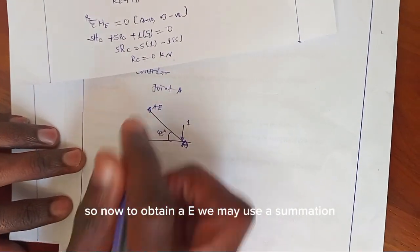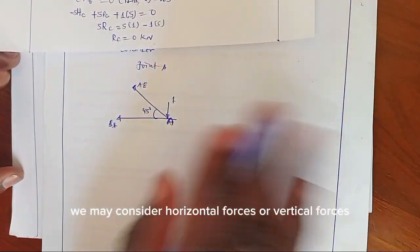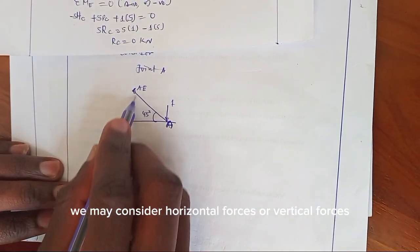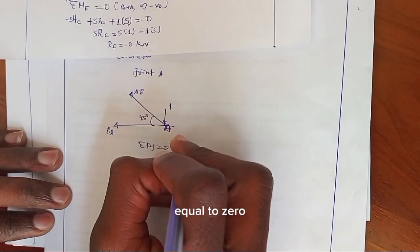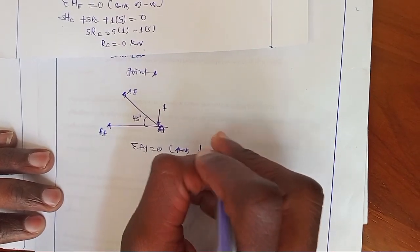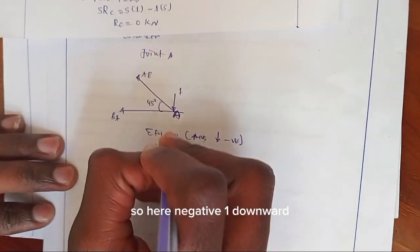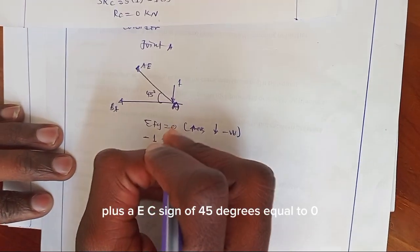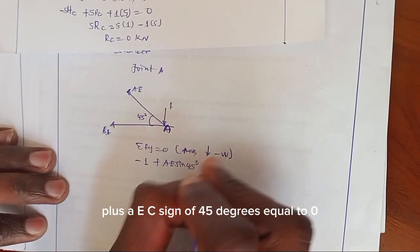Now to obtain AE, we may consider either horizontal forces or vertical forces. Let's consider summation of vertical force is equal to 0. Positive, negative. So here negative 1 downward plus AE sine of 45 degrees is equal to 0.